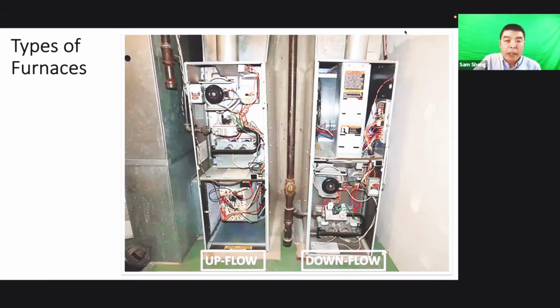So for the gas side, we see the gas pipe here, and this is the gas supply, and it goes through the gas valve here. Normally the thermostat controls the gas valve to open or close. When the thermostat calls for heat, with this furnace we have an inducer motor, and the inducer motor will start.